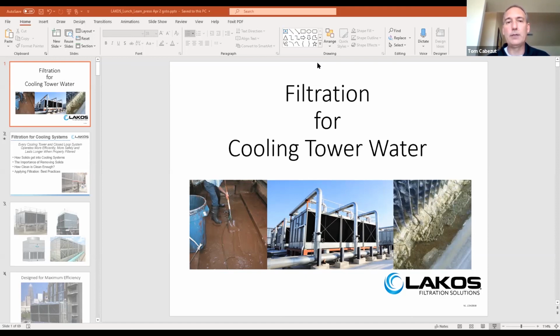Maybe you have one that's down that doesn't have water in it. Maybe they're servicing it for whatever reason. We can zero out that zone, so as it alternates through, let's say, a 3-cell, it will only alternate between 2 cells. So hopefully that answered your question. We, as a factory, will provide a PLC to do the controlling. If you choose not to use our controller, then you guys can set up whatever you would like, but we would prefer, obviously, to have the PLC control it. So hopefully that answered your question, Oliver.